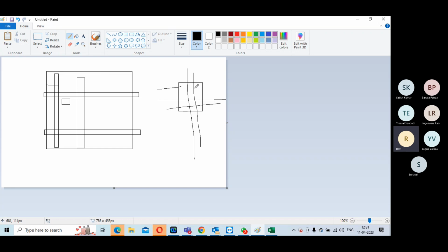When you are actually adding this, you cannot add one over here and one over there. It should be aligned so that this power route is continuous. When you are placing the floor plan, you have to take care that these are properly aligned in the vertical and horizontal direction. Otherwise you will have to connect manually. I'm talking about when you are doing floor plan, this should be aligned properly.